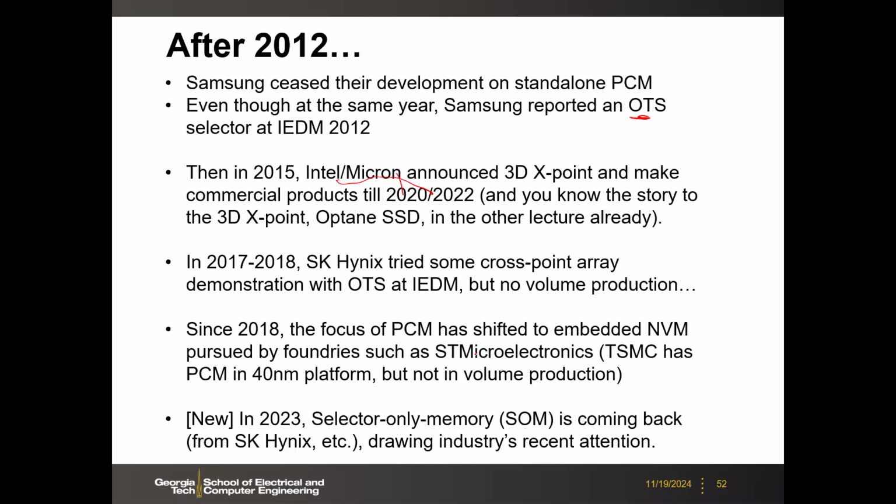They want this for the automotive microcontroller, right? So you need the embedded non-volatile memory. So the same market as the RRAM we talked about earlier, right? So ST's bet is on the phase change for the same market. Okay. TSMC has also had phase change memory development internally. They had the 40 nanometer phase change memory, but not in volume production as of today.